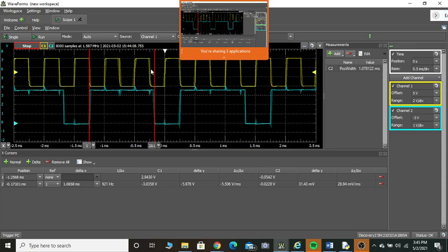These trigger signals are not considered because whenever you are applying the trigger signal, the output is still in quasi-stable state. What do you mean by quasi-stable state? Output high corresponds to quasi-stable state in 555 timer. Since the output is high here, when the output is high, if you apply a trigger signal, it will not consider it.